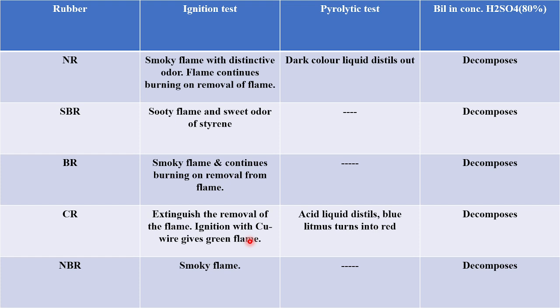You know that usually halogenated rubbers like chloroprene are used for fire retardant applications, because the halogen makes further propagation of the flame difficult, and the formation of radicals scavenges further radical generation, and it will extinguish the flame.